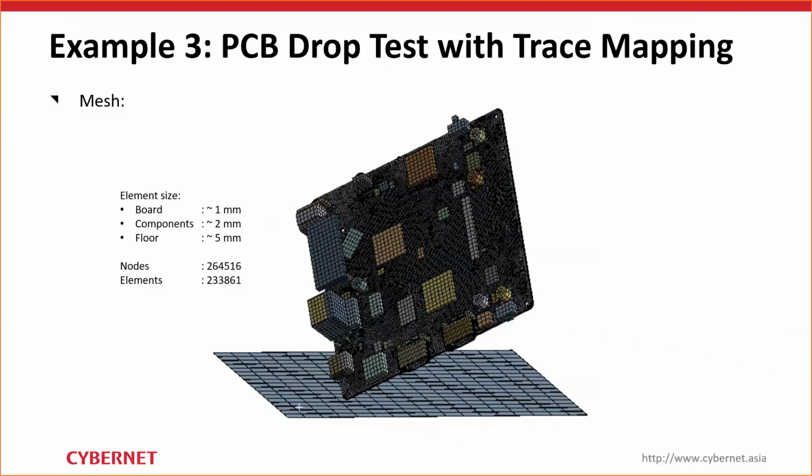And then one thing to note is that in Ansys, there are a lot of mesh controls that can be used to properly mesh your model. Sometimes your design is not going to be as simple as this particular PCB design. Sometimes when you are involved in a design with many curvatures, for example, like a car body or something, you need a proper mesh setup. And therefore, there are a lot of settings available inside Ansys for you to go through in order to get the desired mesh. Now, for this analysis, ultimately, the number of elements and nodes are about 260,000 and 230,000 respectively.